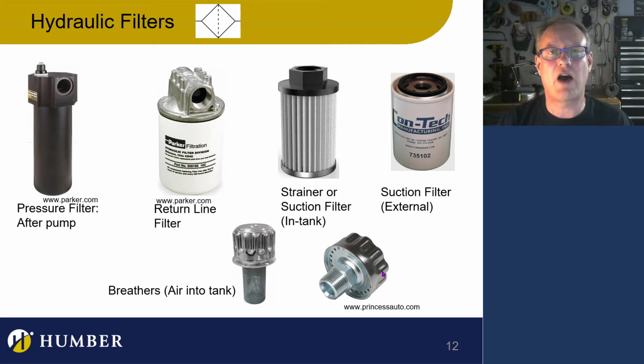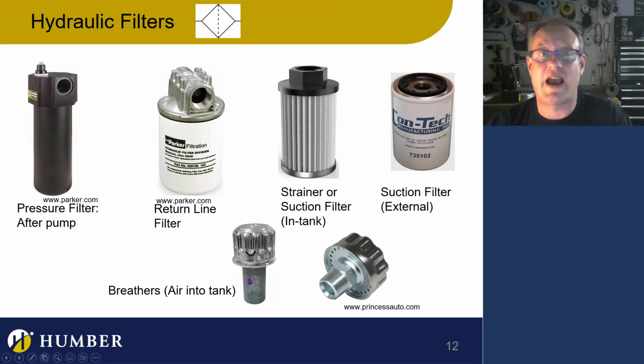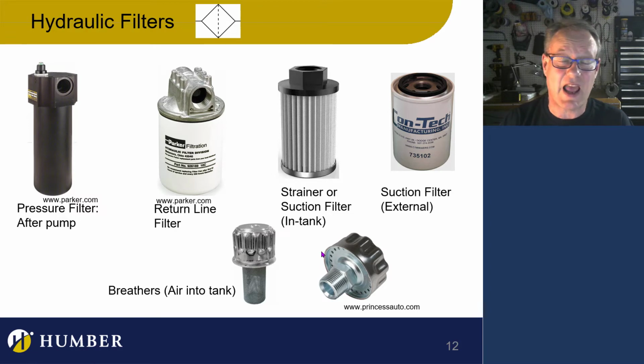So we have to allow air to get in and out of the tank easily without any pressure differential. We don't want to create a vacuum in there. Certainly, we don't want a vacuum in our tank at all. You never want a vacuum with hydraulic fluid, period. There you go. So you're going to put a strainer on the top of the tank, but you also want to filter that because it's sucking in air, right?